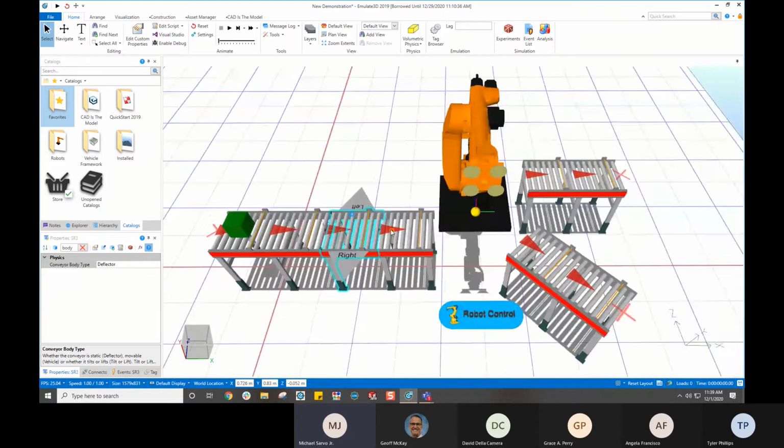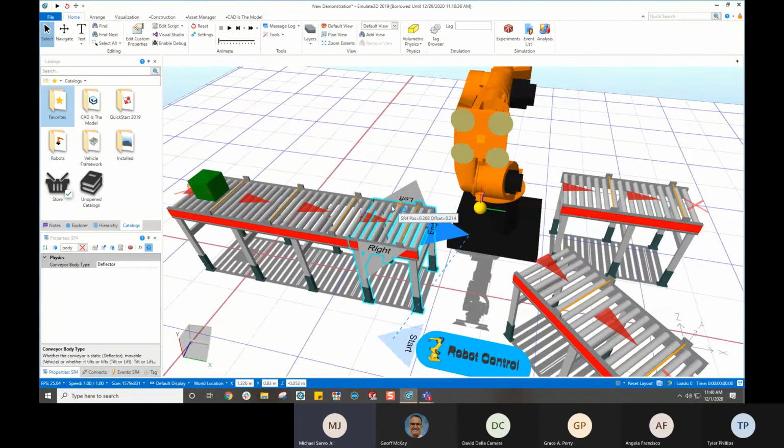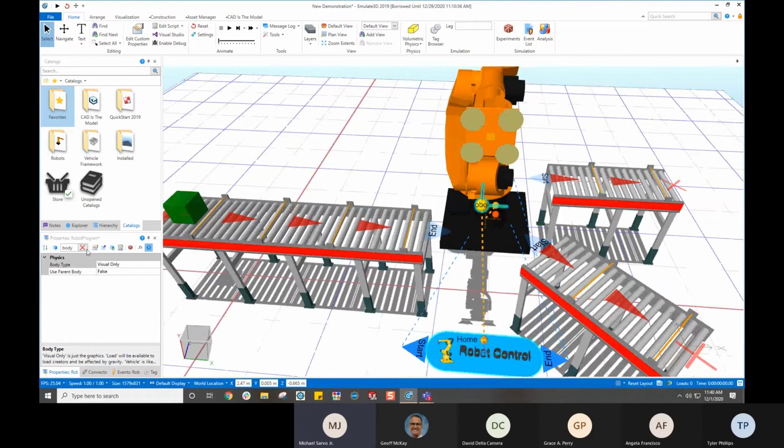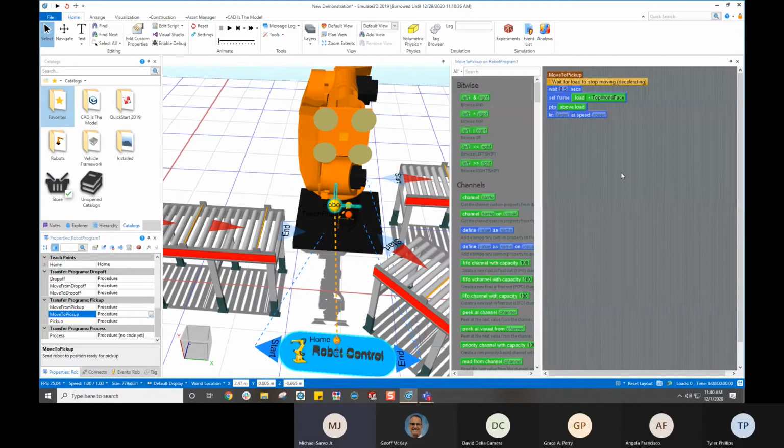So one example is something that I've seen a lot of our users do is they will examine the mass, because the boxes or whatever the loads happen to be, they do have a mass property, and the robot control, right, there's this drag and drop programming language, and if I just open up one of these, this is the first signal that goes to the robot, executes this little bit of code. And I know everything about the load that we're picking up because it's an argument that comes into this coding environment. And I can say, hey, load, how much do you weigh?